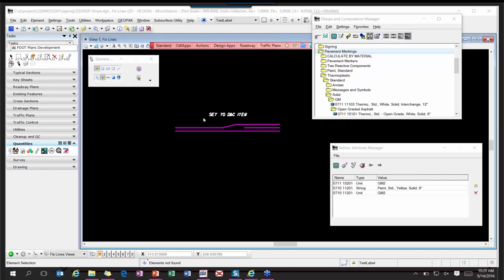Open graded versus other surfaces. Basically, it has to do with the type of surface, whether or not it's open graded. You have to have a certain thickness for the thermoplastic when they place it and lay it down. When you place it on the open graded surfaces, the rocks and the asphalt are not as small as the other surfaces. So open graded, those are bigger. So it kind of falls between the cracks and you don't get the thickness.